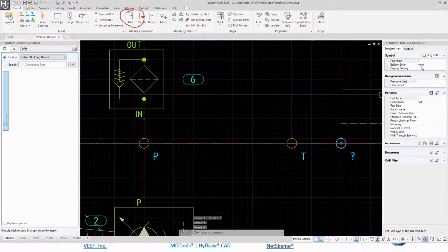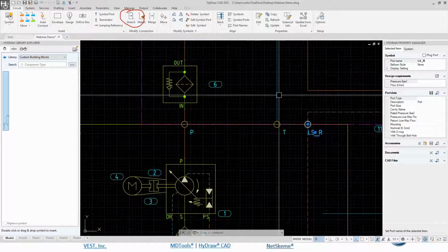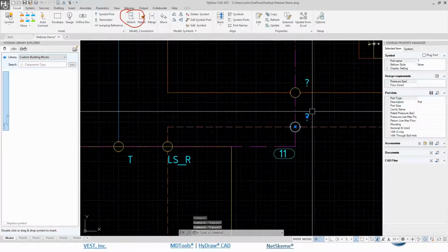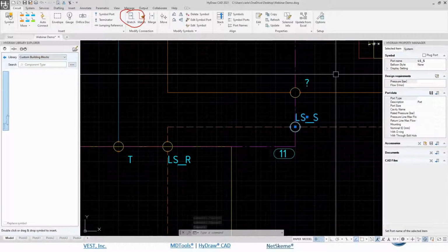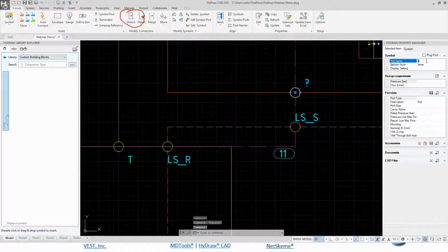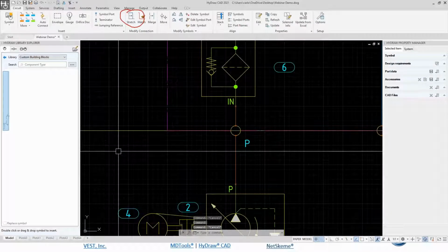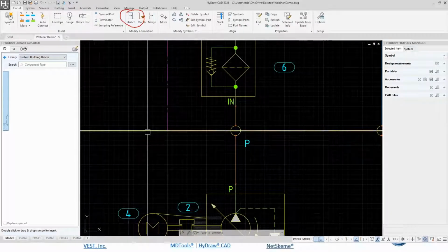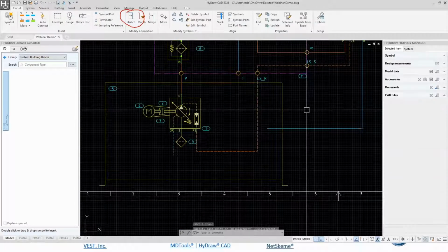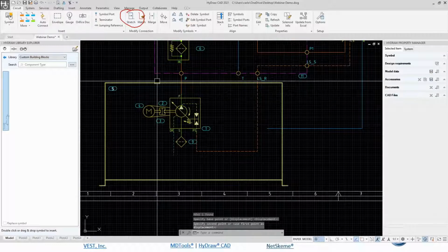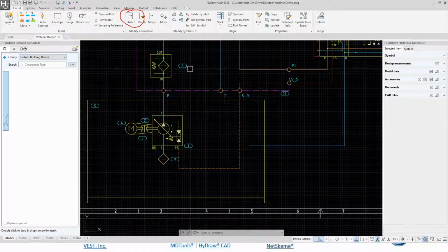And this one will be my LS side reservoir pump. And this is my LS side sectional valve. And that's my P1. And that's it. In this case, I made the reservoir overlap. You can just move it down if you don't want to see lines overlapping, or you can trim the line of the reservoir as you prefer. This is just pure AutoCAD functionality.